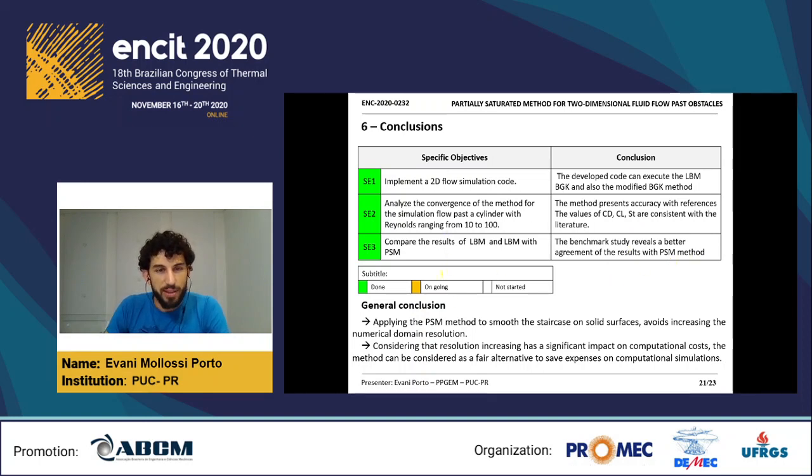And everything that we found here with PSM means that applying the PSM method to smooth the staircase on the solid surface avoids increasing the numerical domain resolution. And considering that increasing has a significant impact on computational costs, the method can be considered a fair alternative to save expense on computational simulations.